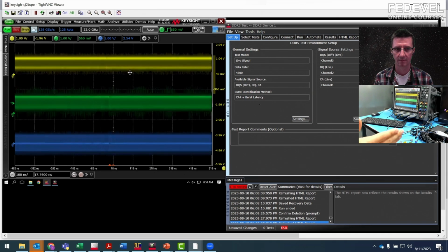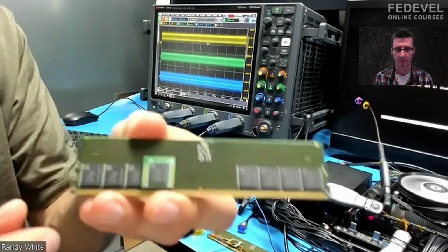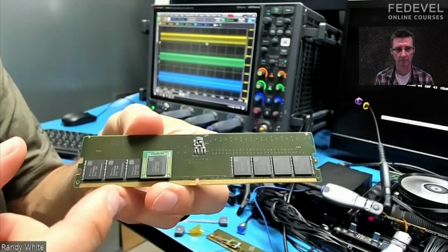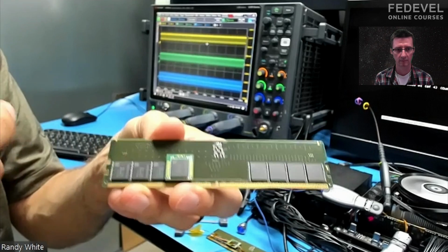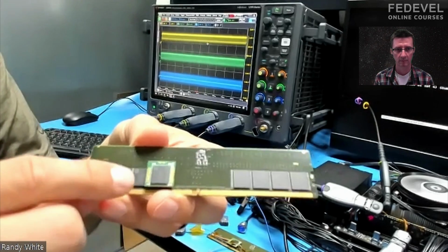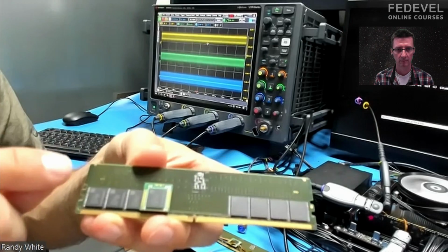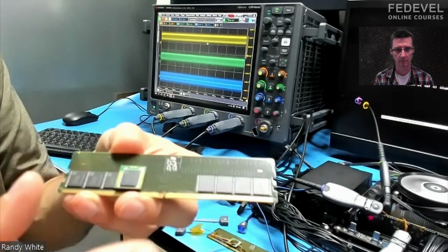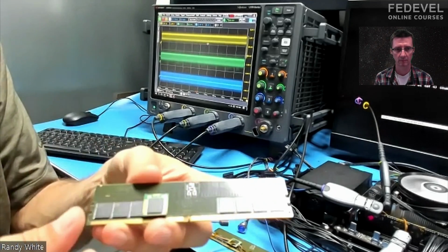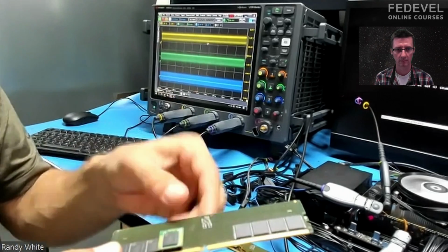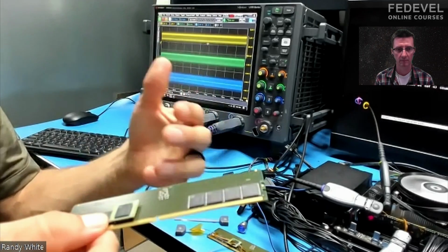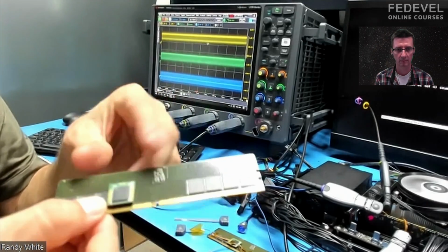In the same way, when we introduce an interposer into the system, like this one here, we design this fixture so that it provides good mechanical signal access, but also we make sure the thickness is designed just right to limit insertion loss or other signal degradations. In the same way that a DRAM package is designed to produce minimal loading on the signal, we do the same thing with this interposer.